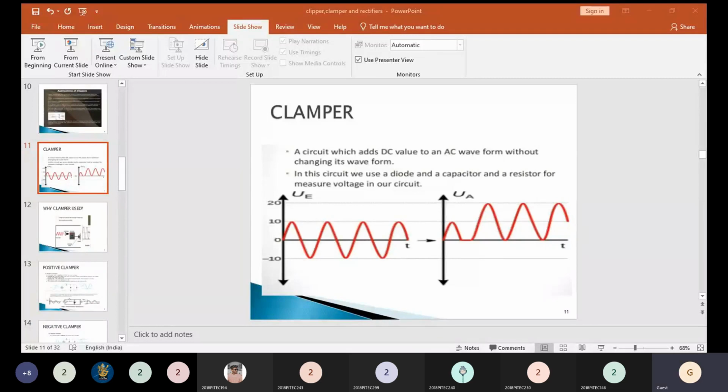For a better power supply, the one with the lower ripple factor is better. You analyze both. For power supply A, what is your ripple factor formula? Ripple factor is equal to VAC divided by VDC. You should be very strong with your formulas, okay? What is your VAC? The ripple is 0.5 VRMS. For VDC, it is 10.